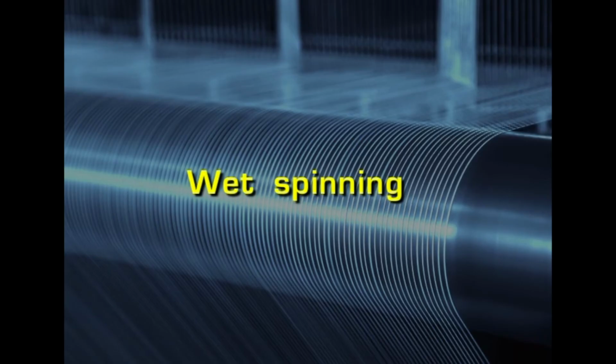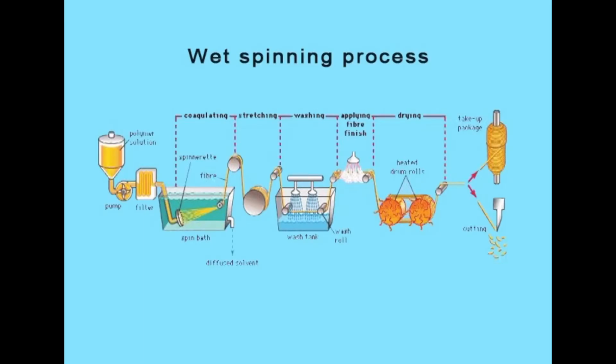The third method of chemical spinning is wet spinning. When the polymer is not in a stage of melting or dissolving in a volatile solvent, then a non-volatile solvent is employed. Since a non-volatile solvent is used, we cannot evaporate it, and so a chemical bath is required in order to coagulate the polymer, so that it comes out in the form of a thin filament. So it requires the chemical bath if non-volatile solvents are used.